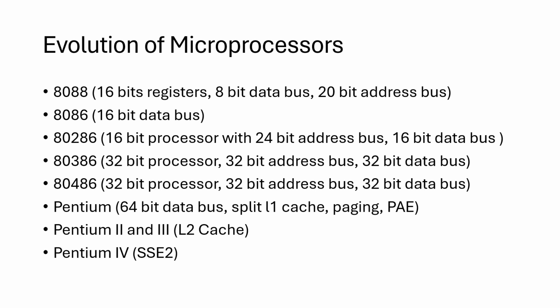So let's try to understand what real mode and protected mode are in the context of the processors. Real mode is something that was there in the 8088 and 8086 processors. Older processors supported these. These processors have a 20-bit address bus, as we had seen in the previous slide, and so they were able to address up to 2 raised to 20, that is 1 megabyte.